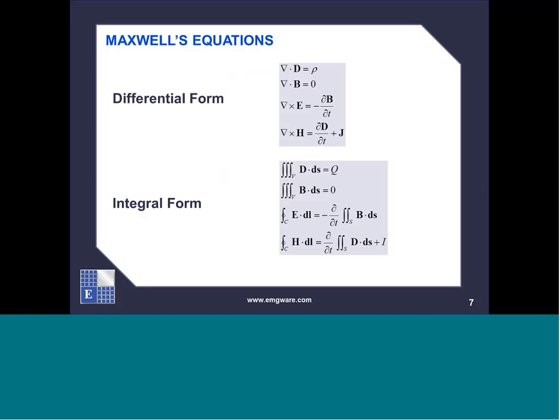Now, all of these things said, Maxwell's equations are the governing, underlying physical equations for all electromagnetic problems. If you remember from a basic electromagnetic course, Maxwell's equations have a differential form. The divergence of D and B vectors, displacement and induction, are rho and 0, and then the curl of E and H are related to minus the derivative of B and the derivative of D, respectively. So these are basically Ampere's law, Faraday's law, and Gauss' laws. The differential form of Maxwell's equations can be cast into an integral form, and if you remember from the theorems of vector calculus, in this case you express the electric and magnetic fields over a volume, over a closed surface, or over a closed curve.